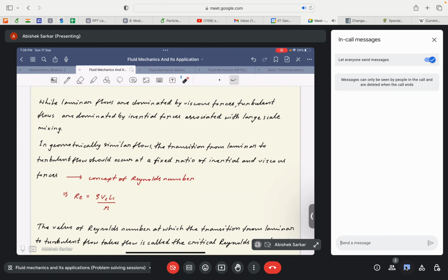They use empirical relations and create different charts and models that can be used to analyze turbulent flow fields up to a certain limit. There's always a limit beyond which the model fails. Different researchers create different models which work in different regimes of Reynolds number, and thus the limitation. There's no universal solution for a certain type of flow field, right? Even for the same geometry, if the Reynolds number varies, then the empirical model breaks down in the case of turbulent flow.